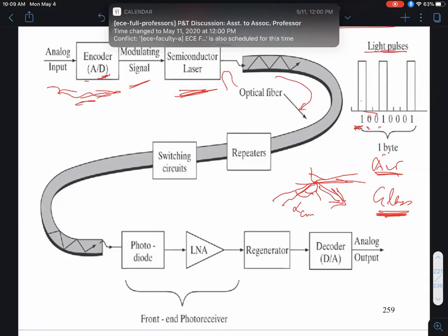That's the basic physics of optical fibers. You make them out of glass. So if you launch these laser pulses at an angle greater than the critical angle, instead of going out into air, it'll bounce back, it'll keep bouncing back. And that's how you transmit the signals over enormous distances. So you have these submarine cables that go under the Atlantic or Pacific, and that's what carries most of the information in the world today. Or when you go from one city to the other, it's all optical, okay?